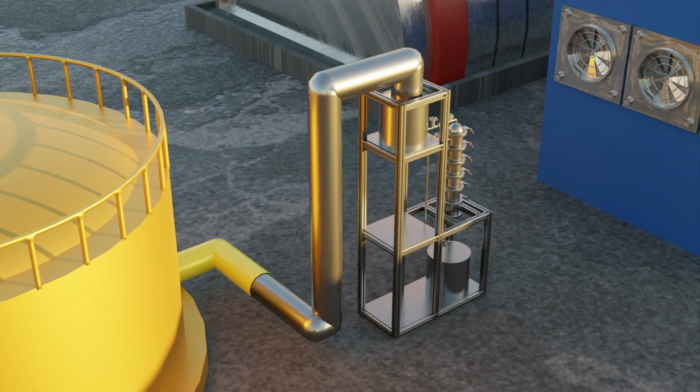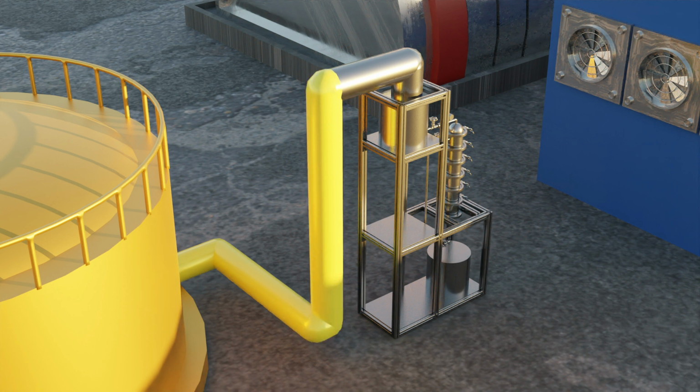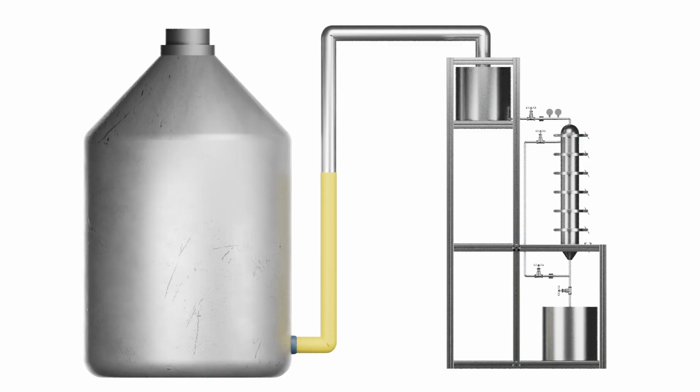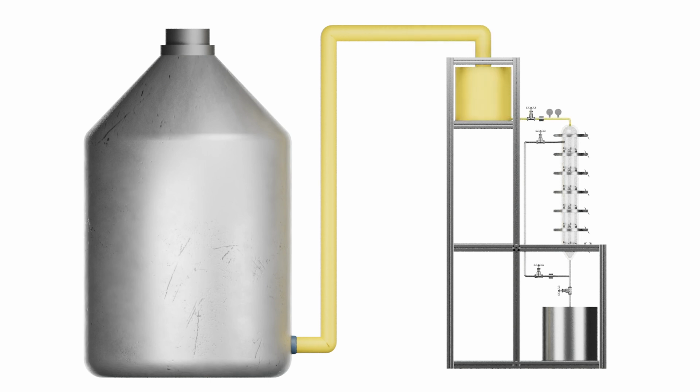Here, our i-Adsorb technology can overcome the limitations of the traditional mitigation methods by integrating after the deodorization treatment process. Here, the refined palm oil is contained in a holding tank, in which an inlet feeds the refined palm oil stream into an adsorption column, comprising a layer of the functionalized adsorbent. The refined palm oil feed stream flows in perpendicular to the functionalized adsorbents by gravitational force.